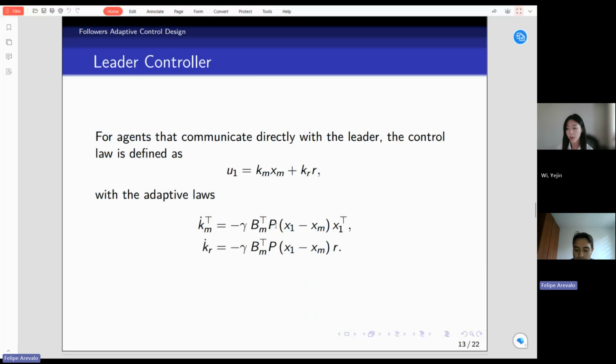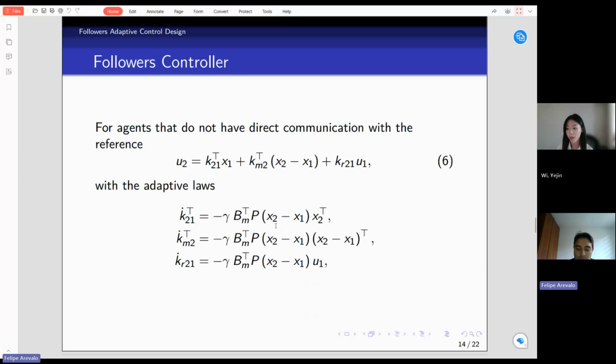So we're considering this case of a follower that has access to the leader or the reference drone, and we're considering a second scenario of drones that don't have communication with the reference. In this case, the information needs to be communicated to the neighborhood, and the objective is to accomplish the synchronization even when we don't have the information of the reference drone. This is a brief extension of the previous case that I presented, but in this particular case, the set of adaptive gains that we are using considers just the information that we can share with the drones that are in the neighborhood of an agent.